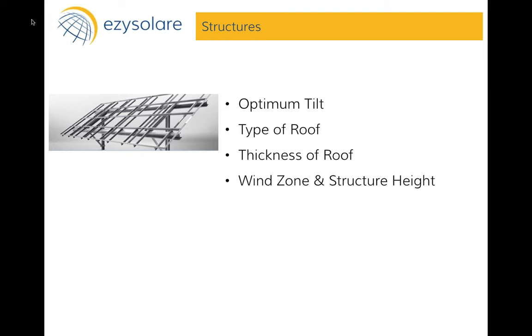Lastly, another parameter is sheathing and temperature. Sheathing basically refers to the outer coating of the cable. Typically, the sheathing should be UV protected, which means that if you are going to lay the cable in an open environment, it will be exposed to ultraviolet rays in the sunlight. And if you want to protect against that, then the cable should have UV sheathing. Otherwise, you should definitely use conduits to put in all the cables, and you should never get cables exposed.